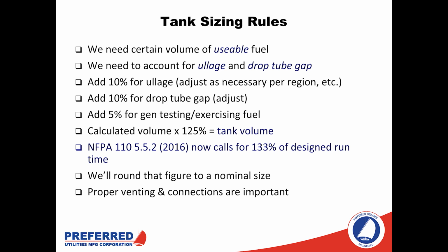tank sizing on. Now, that selection could also be modified depending on how large the day tanks are in the system. For a typical single day tank, single generator system, we wouldn't necessarily need to factor that in. But if we're looking at a system with multiple generators, multiple day tanks, we may want to take the size of those tanks into account when we're sizing the total amount of fuel in the system.